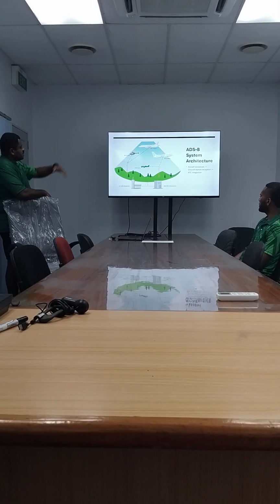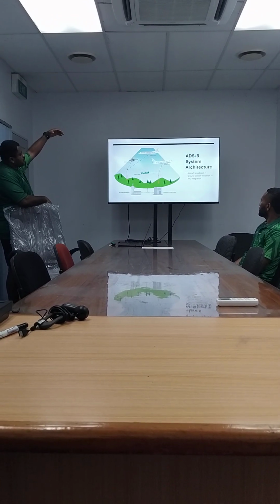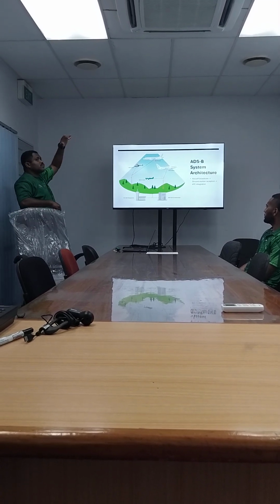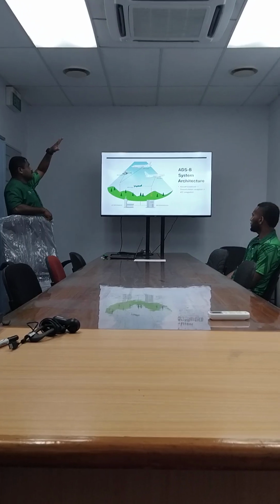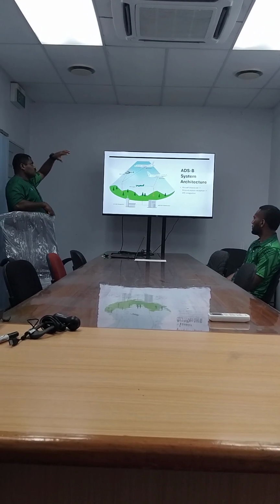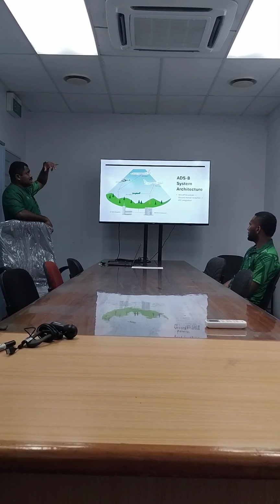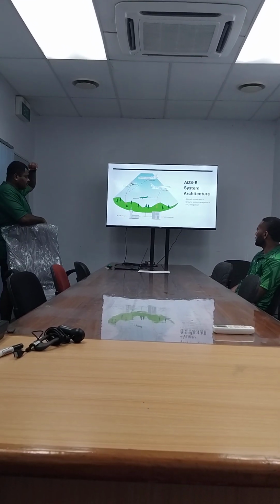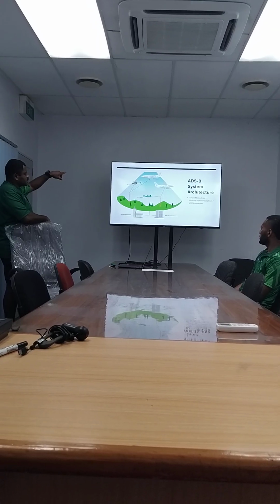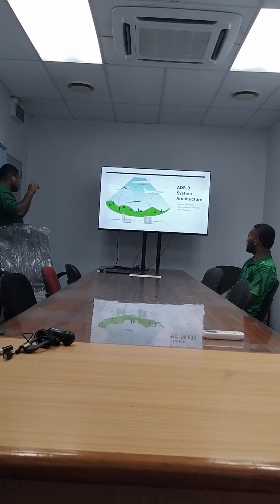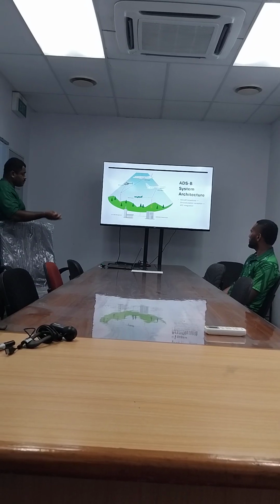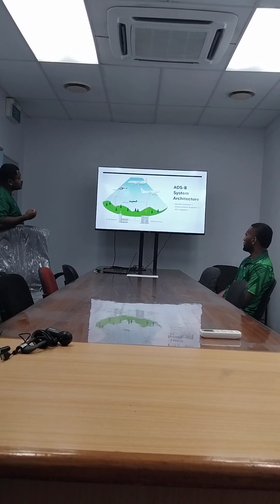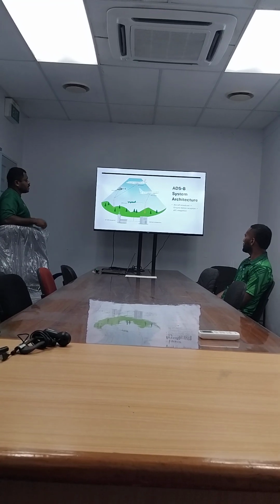So basically, position is established by triangulating. Firstly, the aircraft has to get its position right, so it needs three or more satellites to triangulate its position. Once its position has been triangulated, latitude and longitude, then only will all the data transmitted be correct. So part of the messages is the speed of the aircraft, type, flight number, the velocity of the aircraft, and the position of the aircraft.